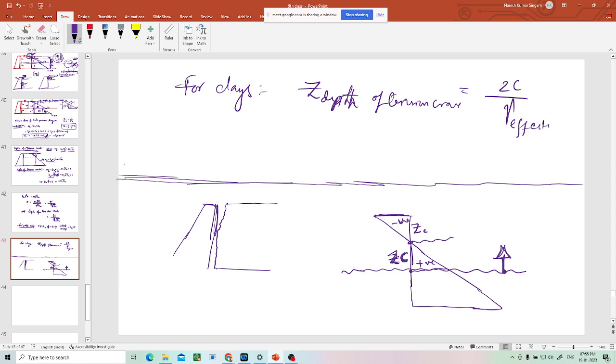So up to this depth, net force will be in the tension. Then at this depth, total force is 0 from this depth. So the net force will be, if you calculate only the area of this, you will get only the net, before formation of the crack. If it is after formation of the crack, then you will have to neglect this.